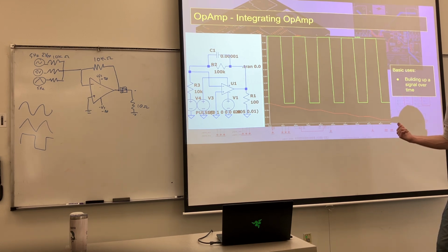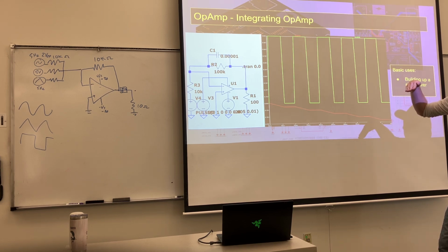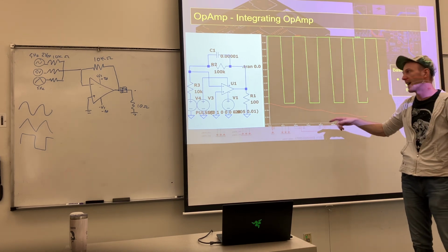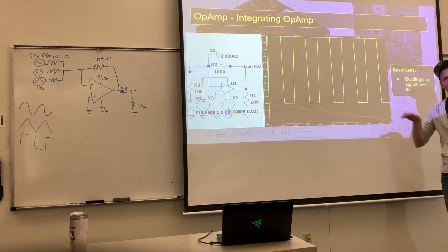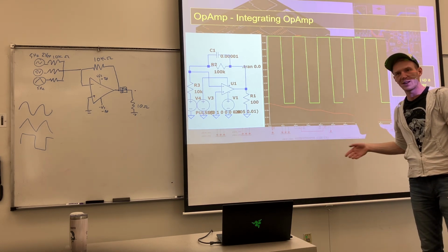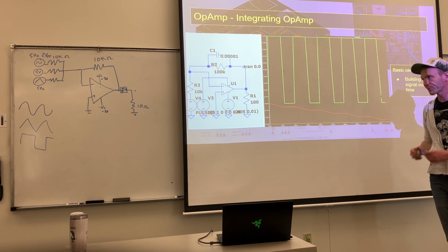This is used for stuff like autopilots, where it's like, I've changed my flap a tiny degree, I'm getting this much lift, my heading is this, I know I need to be over here, but what you don't want is a system which is going flap here, flap here, flap here, just instantly changing back and forth. So if you had the integrating portion high, this continues to build up if you're oscillating about one point, and will provide negative feedback to say, maybe stop switching back and forth between these 2 points a million times and causing the aircraft to go woo. It says, maybe you should chill out and find a place in the middle of that.